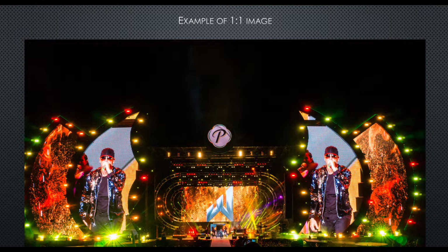Here's a good example of one-to-one pixel mapping done to all the LED screens, except where you see the live camera, where we were showing the artist. This was obviously scaled because that LED screen was not in the right aspect ratio. However, we maintained the aspect ratio for scaling using something called Barco E2 or Novastar's newer processors like the NovaPro UHD Jr. or UHD. Those are able to scale while maintaining your aspect ratios, and scale on different layers.